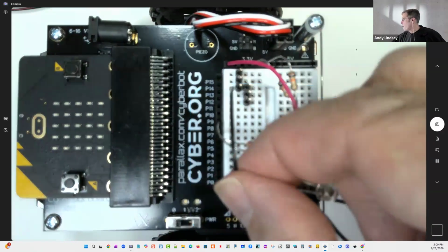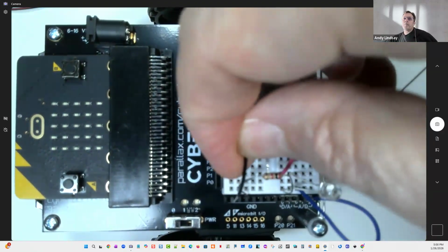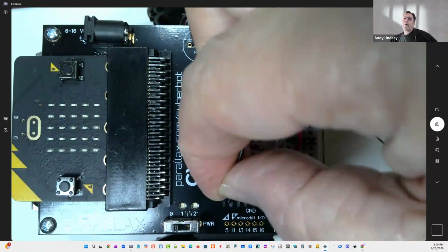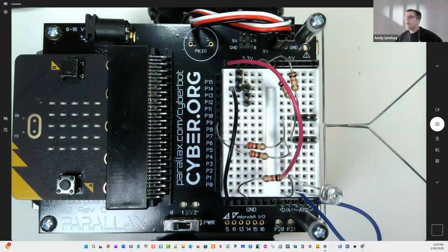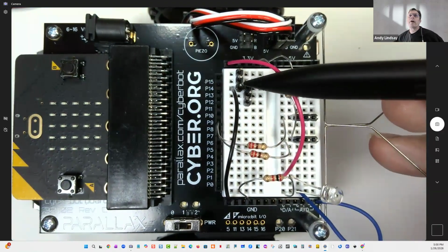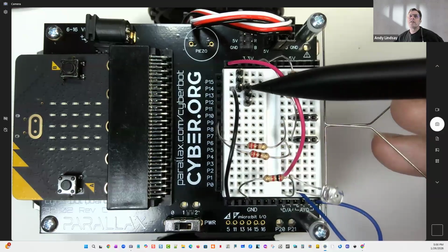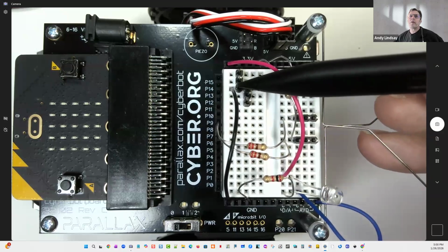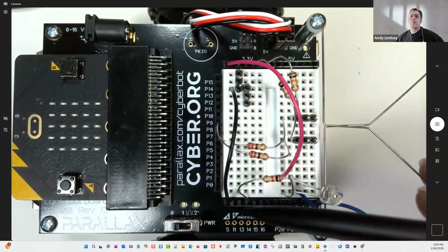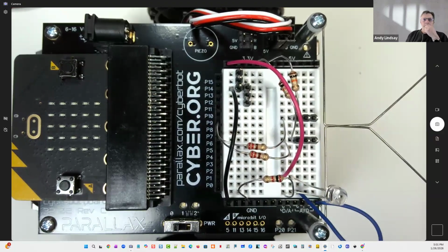And our black wire is going to go clear down to the black GND or ground sockets that are below the breadboard. So what I just did was I connected the black wire to the third row down where the two pins from the upper and lower 3-pin headers are. And so it's taking that and it's jumpering down to the ground pin right there.